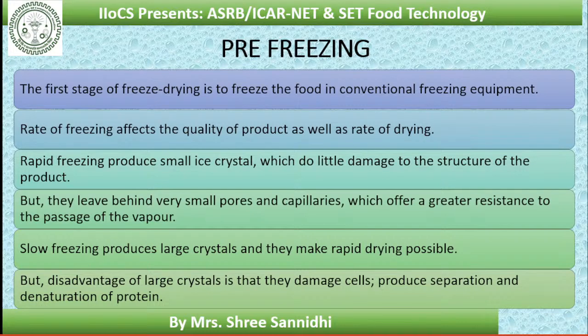the ice crystals, right? That's why bigger ice crystals are formed, but these bigger, larger ice crystals might damage the cells of the food. That's why rapid freezing is preferable in freeze drying. Okay, rapid freezing produces small ice crystals which do little damage to the structure of the product,